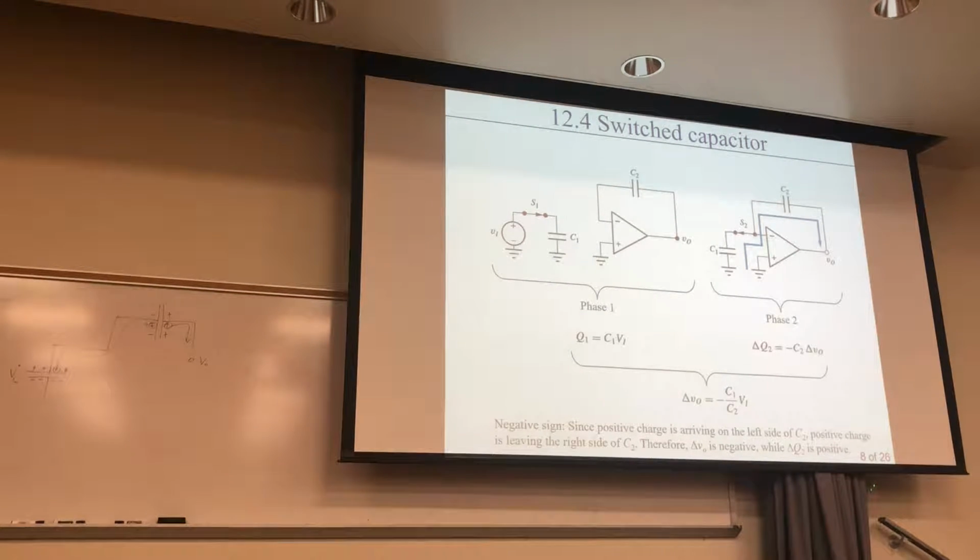It's changing downhill from a high value to a lower value. Like the voltage across here is decreasing in time, right? Because each charge that's leaving is decreasing in time. Eventually, since the upper side is grounded and that's grounded, they have the same potential, then eventually you won't have any charge stored in that capacitor. All the charge will have dissipated off.